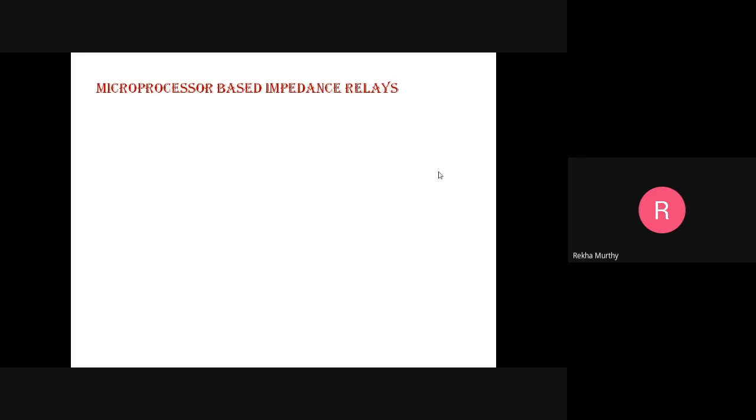One technique is to use IDC and VDC for the computation, as they are proportional to IRMS and VRMS. VAC and IAC will be rectified by using a rectifier circuit to obtain VDC and IDC. These rectifiers make use of ICs and diodes. Then the line impedance will be computed, and the microprocessor issues a trip signal to the circuit breaker if the fault point lies within its protected section.